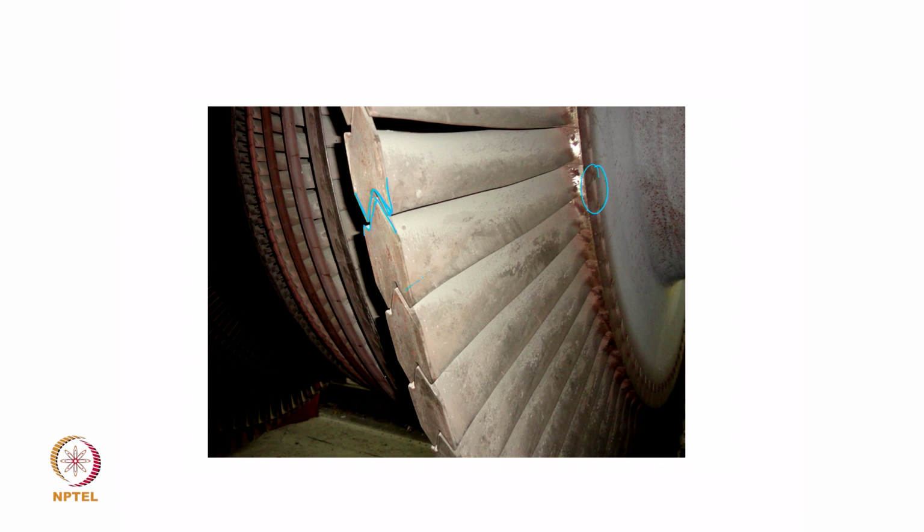So, you can see that here, and as the blades vibrate, the lateral vibration of the blades also causes simultaneous torsional motion, right. So, the blade will also move this way and also move laterally, and the net motion is going to create